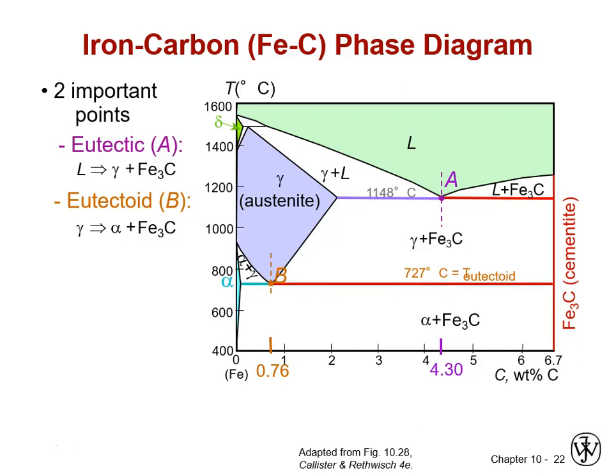So you can see that the eutectoid tie line goes all the way across from 0.76 weight% carbon to 6.7, which is where we have another intermetallic or stoichiometric compound, Fe3C, which also goes by the name of cementite. So it's another one of those mineral nomenclatures. And again, we usually treat it as its own component in the phase diagram, as if it's another metal.